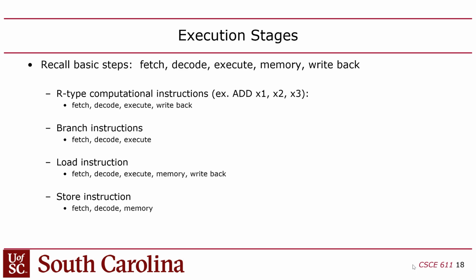And the significance of these is that each one of these operations is the most work you can do in one clock cycle. These operations were sized according to the critical path delay. They're all sized so their critical path delay would be whatever your cycle time is, right? So you take an instruction and the CPU decomposes it into 5 steps at most. Not all of them are used for every instruction.